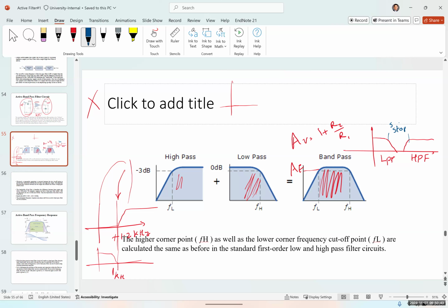And this is actually what we call the notch filter or a band stop filter. So band stop filter is the opposite of a band pass filter, okay? We want to pass every other frequency, but block a certain frequency, which here, for example, could be between 2 kilohertz and 3 kilohertz.